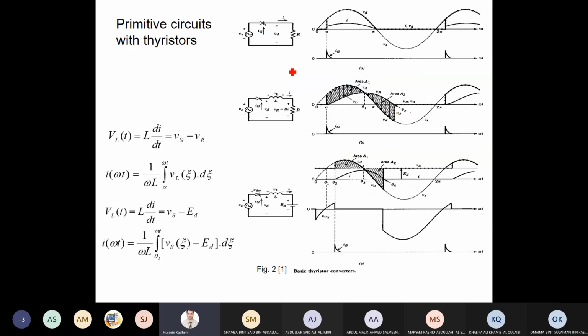Now, you see here this circuit with one thyristor instead of a diode. We have R load, inductive load, and back EMF. These circuits were discussed in the previous module, and we mentioned that if it is a diode, the pulse appears across the supply, the load, and so on. But when we have a thyristor, positive voltage comes here, but still does not appear across the resistance.